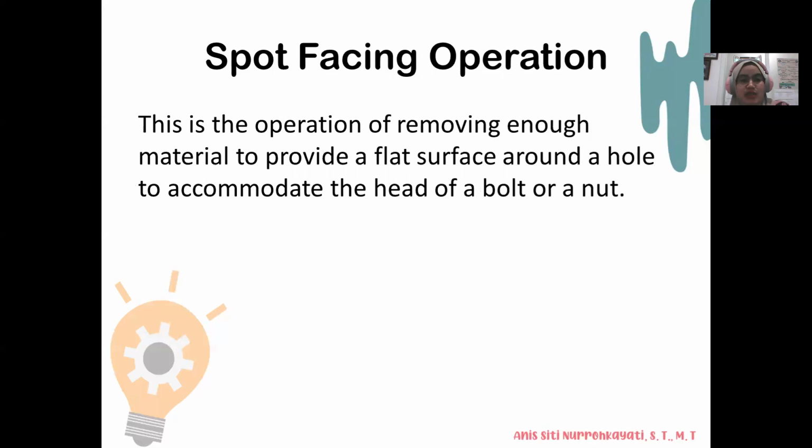Next is spot facing operation. This is the operation of removing enough material to provide a flat surface around a hole to accommodate the head of a bolt or a nut. A spot facing tool is very nearly similar to the counterbore. This operation is like a counterbore, it is similar.